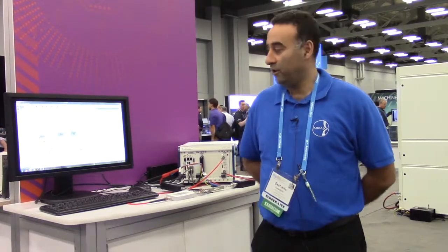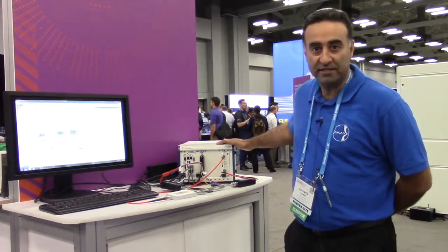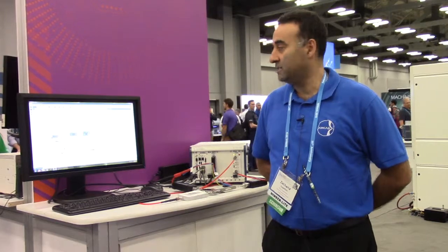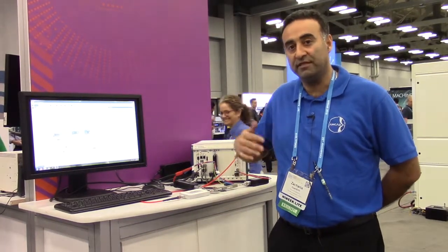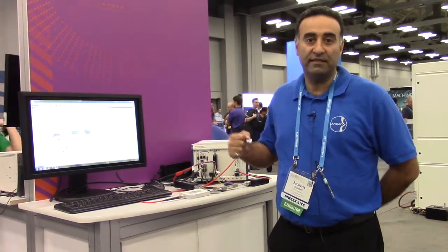We are presenting IQStar, a software to characterize 50-ohm devices using a PXI chassis. So this software is meant to be a measurement platform for 50-ohm devices. And the idea is to be able to do different measurements as parameters, 1 tone, 2 tone, video bandwidth, and modulated signal under the same sequence. And the idea also is to create a sweep plan where we're going to be able to do different measurements at the same time and get all this data set at once.